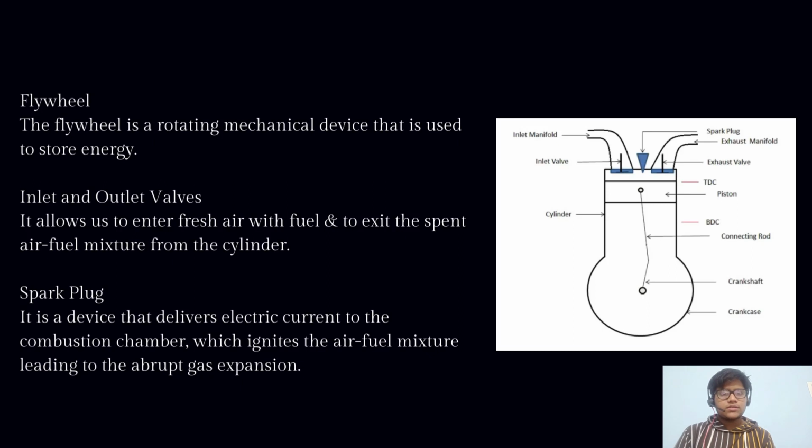Now let's understand the next key component, that is the spark plug. Spark plug is used in engine ignition. The main function of the spark plug is to conduct high potential from the ignition system into the combustion chamber to ignite the compressed air fuel mixture. It's fit on the cylinder head. The spark plug consists of a metal shell having two electrodes which are insulated from each other.